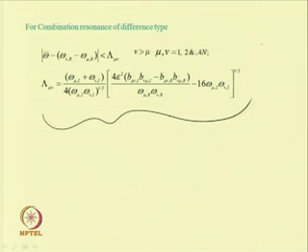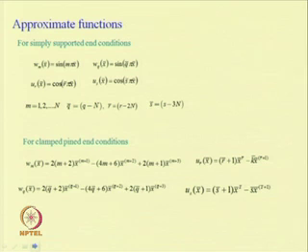So, using these expressions, let us take a physical example and see how we get the instability region. Here we can take W m, W q, U r and U s as the shape functions of the corresponding Euler-Bernoulli beam with the boundary conditions. For example, in the case of simply supported end conditions, we can take W m of x bar equal to sin m pi x bar. Similarly, W q of x bar, in the transverse direction, equals sin q pi x bar. Similarly, U r of x bar equals cos r pi x bar and U s of x bar equals cos s pi x bar. These equations will be used in the integrations to find the mass matrix and stiffness matrix of the system.